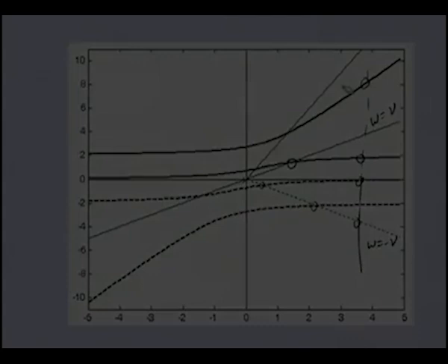Similarly, if we draw another line, omega equal to minus nu, it intersects here, this is the first backward critical speed, and this is the second backward critical speed. So you can see that we got 3 critical speeds, 1 forward and 2 backward, but another forward was absent.